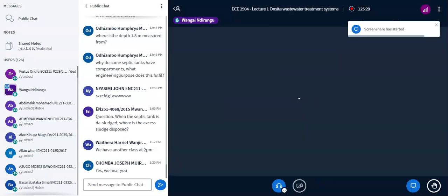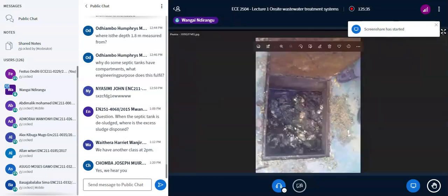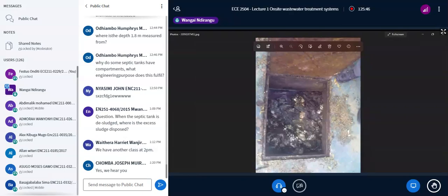Now, you can see here a bit of water. What was causing this is that they were using some chemical, some detergents, washing chemical. When this chemical comes with hot water that is used for laundry, it forms some woolly material. That's what you're seeing here. So again, the characteristic of the water being treated becomes important.